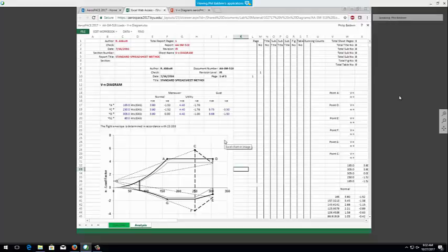And what you see is essentially your wing loading is extremely important. A high wing loading massively increases your power. And what's happening in terms of your launch speed is your required launch speed for a minimum level of power. Basically, we have this kind of threshold effect where if you throw too slow, you start needing more and more power very, very quickly. And so a very weak launch hurts you a lot. And that's pretty visible here. You see that the power required is shooting up drastically.